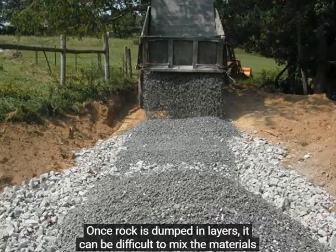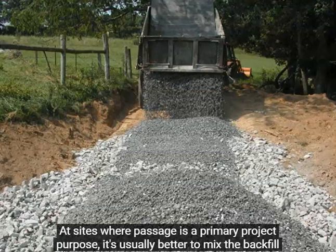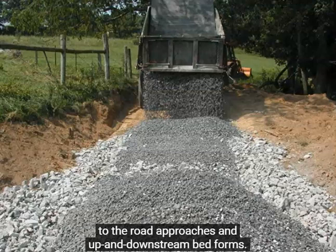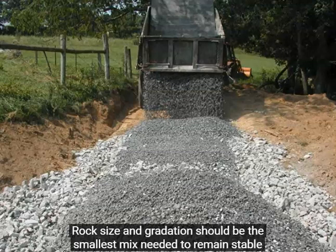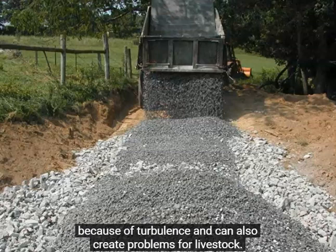Once rock is dumped in layers, it can be difficult to mix the material so that the resulting stream bed surface is well graded. At sites where passage is a primary project purpose, it's usually better to mix the backfill at a quarry or staging area, place it into the cut, and blend it laterally to the road approaches and up and down stream bed forms. Rock size and gradation should be the smallest mix needed to remain stable under prevailing flow conditions. Bigger isn't necessarily better for passage because of turbulence and can also create problems for livestock.